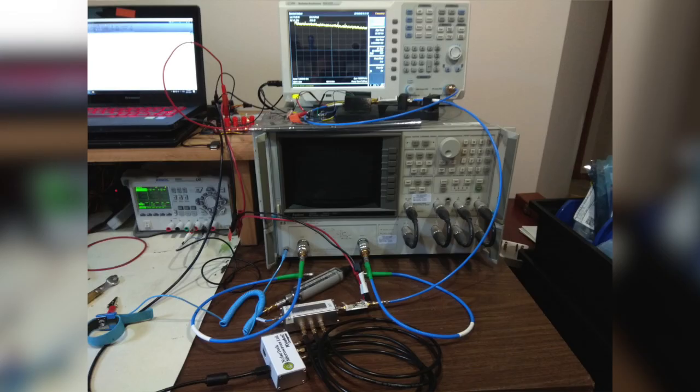So before we move on to the next step, all the steps that have built up to this have been for the purpose of calibrating the noise of our measurement equipment itself. So now we're ready to add a device under test. The first thing you want to do, step 9, is measure the 2-port S parameters of your device under test. The picture here does not show it connected, but you would power up your VNA again, calibrate it, measure your S parameters of the device under test, or your amplifier or low noise amplifier, and then reinsert it into the spectrum analyzer setup below, between the impedance generator and the spectrum analyzer. And then you can leave the noise source off for the remainder of the tests.